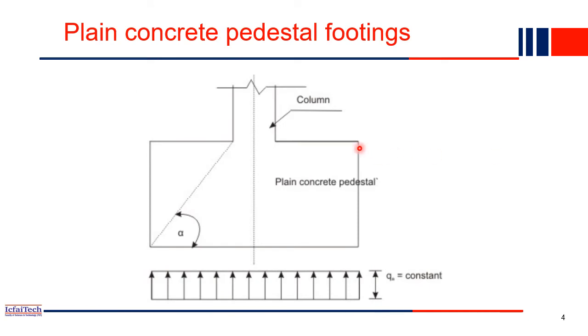Now we'll see in detail about each of these foundations. So the first foundation type is basically the plain concrete pedestal foundation. So what is plain concrete pedestal foundation? A plain concrete pedestal footing or foundation is very economical for the columns of small loads, or the pedestal, without any longitudinal tension reinforcement. You can see here this type of pedestal footing we can use when a very small amount of loads are coming, then we can go with plain concrete pedestal footing.